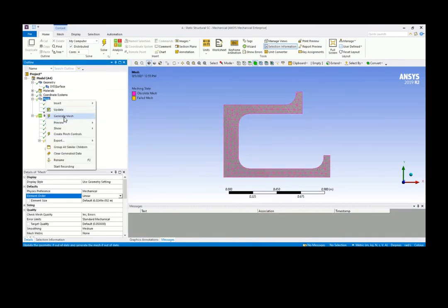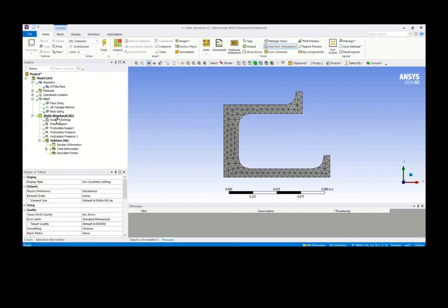If you are looking into stress, you should use quadratics. So here we are just demonstrating adaptive meshing. And we are using total displacement to adapt the meshing. So here we try to use linear, which is faster. So we have a fixed support.